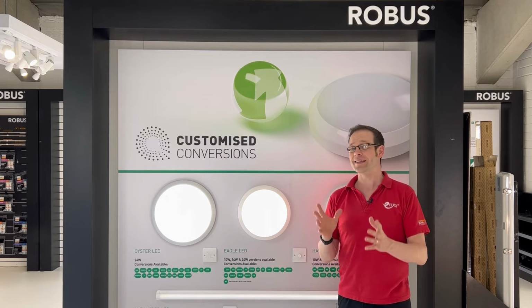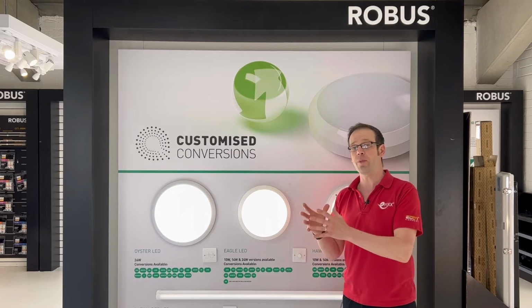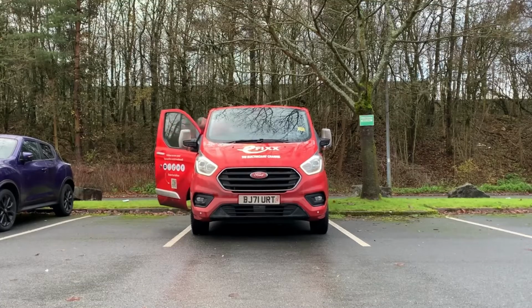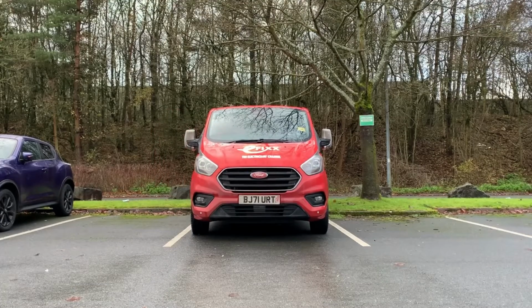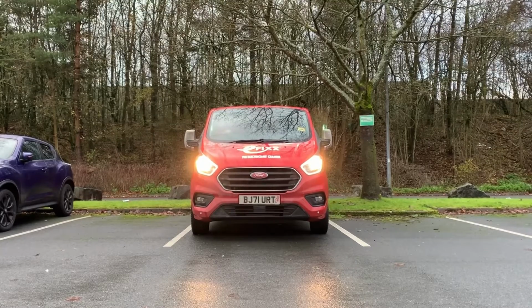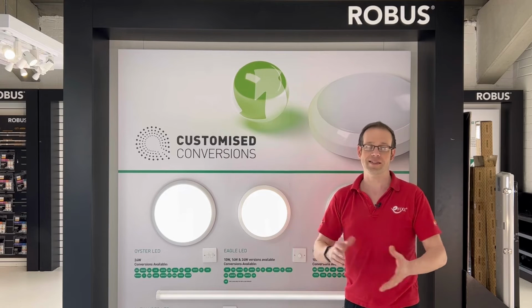The first of these is glare. The basic concept of glare is that it's a comparison between how bright a light source is when compared with the background that it's shining in. You'll have seen it yourself. If you've ever noticed people driving around in the daytime with their headlights on, they don't seem very bright because the surrounding surfaces are already well illuminated by the sun. If, however, you see those exact same headlights at night, they can be quite dazzling. Same light source, but in a darker background, and so the glare effect is larger.